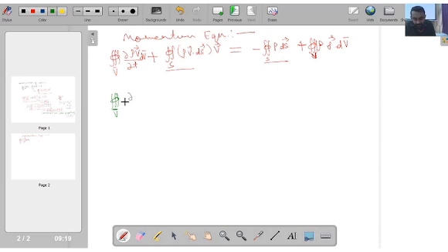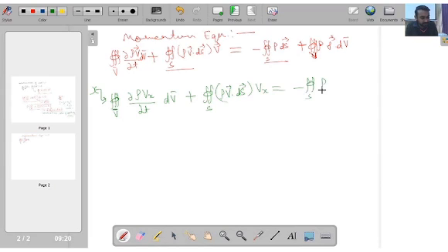So that's why I will try to write individually over here. If I have to write the x momentum equation, then I can write del rho vx by del t into dv bar plus the surface integral of, so this is my x component of the momentum equation. Let me first write the x component, then I will use the transformation from surface integral to volume integral. So this will become the surface integral of rho v vector dot ds vector times vx, then